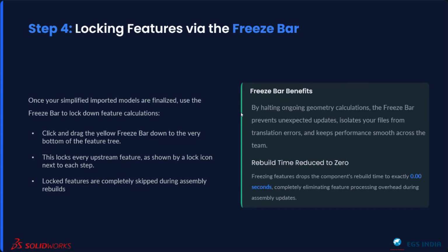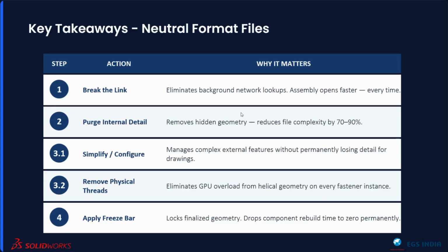So we saw how to clean up your step or imported files over here. The first is where you break the link, which basically eliminates the background checks every time you rebuild or recalculate your assembly. You're going to remove all the internal details that are hidden from you.